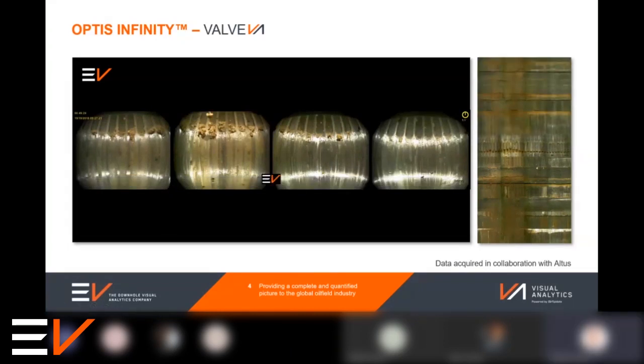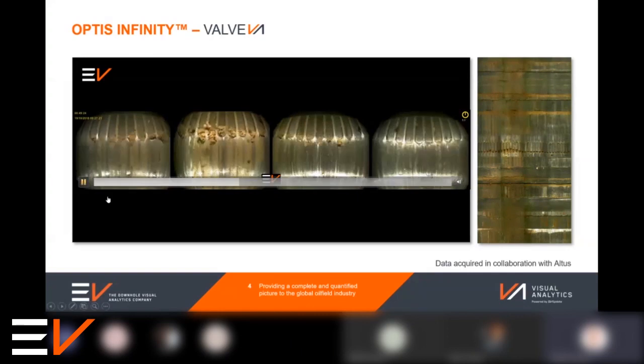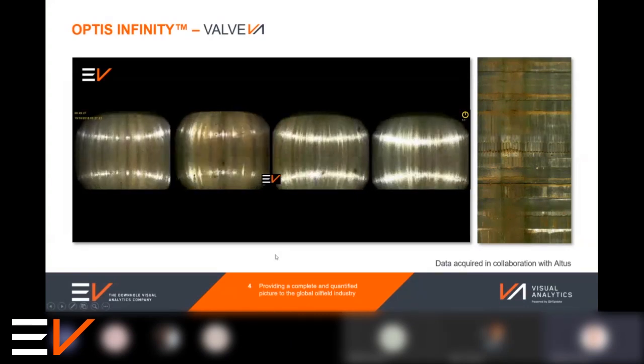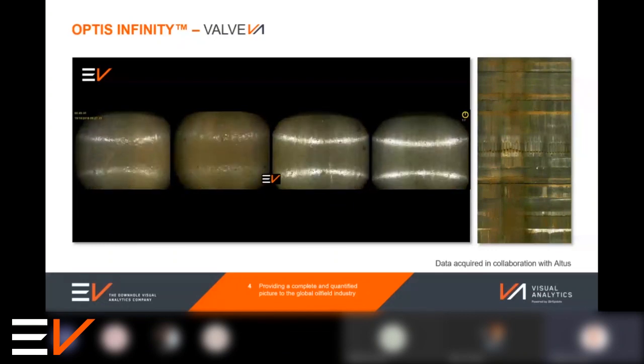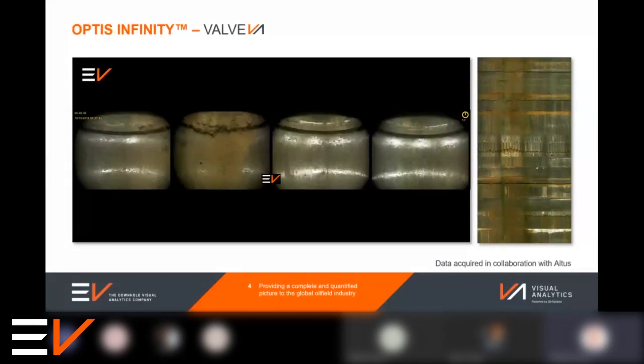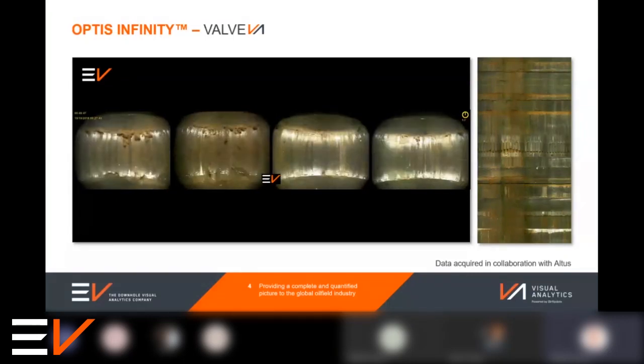But because that moves and behaves in a different way to the objects at the pipe surface, it's quite common that when we do the image mosaicing, as we call it, those loose particles actually are eradicated from the final image. So there's a twofold system there, that firstly, we're less sensitive to contamination because we're not trying to look as far through the fluid, but also with the post-processing, we're actually able to eliminate some of those unwanted features and get to the main event.